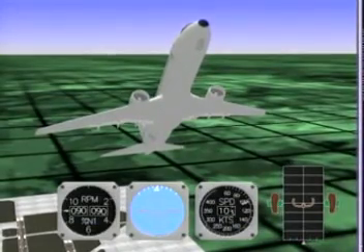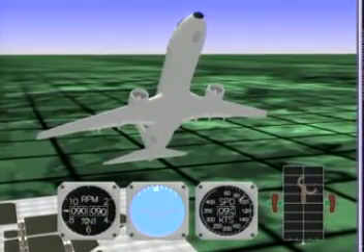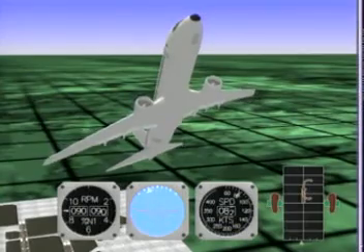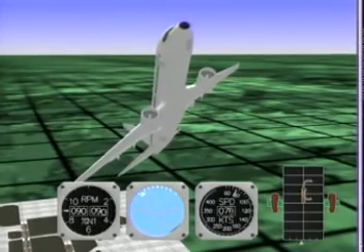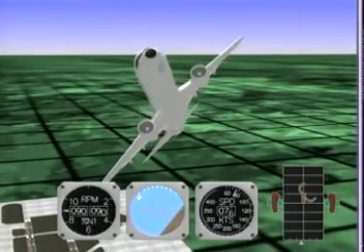If at this point you cannot immediately get the pitch rate under control, there are several additional techniques which may be tried. The use of these techniques depends on the circumstances of the situation and the airplane control characteristics. You may also control the pitch by rolling the airplane to a bank angle which starts the nose down, normally not to exceed approximately 60 degrees.